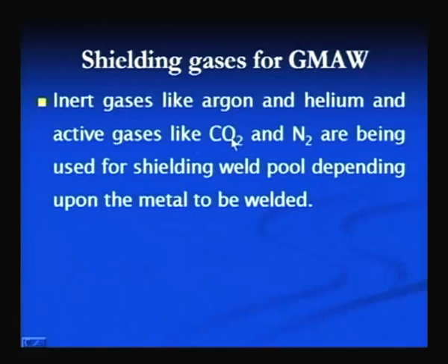Then shielding gases, as I have told you earlier, in addition to the filler metal and the power source also play a significant role in successful welding of the reactive metals and the ferrous metals, because these shielding gases provide the desired protection to the weld pool from the atmospheric contamination, and the shielding gases here can be used in the form of argon or carbon dioxide.